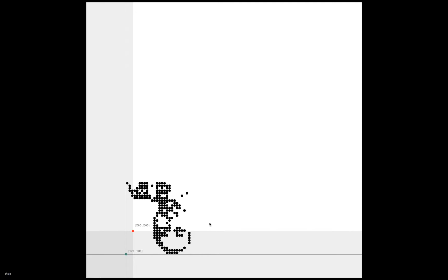After exporting, it's going to export a text file with the new origins, which is going to go into the G code generator later, saying to the generator that, hey, I want at the beginning after homing to move the pen head to this position and make it 0, 0. So in this software, you can see the maximum limits with M, and it's like 20 centimeters by 20 centimeters on both axes. Everything is in mm here.